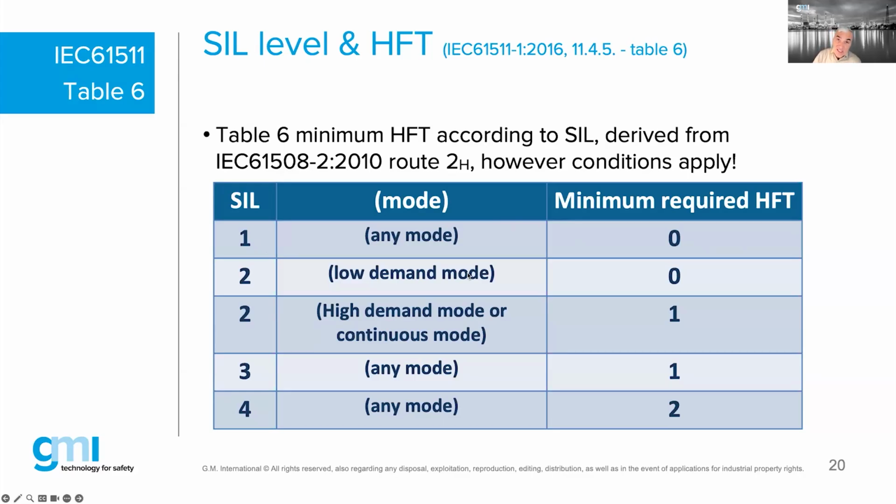The hazard will happen less than once per year to activate your safety function, and it doesn't happen more than once per year. We call this low demand. Still, you are allowed to use a single 1 out of 1.